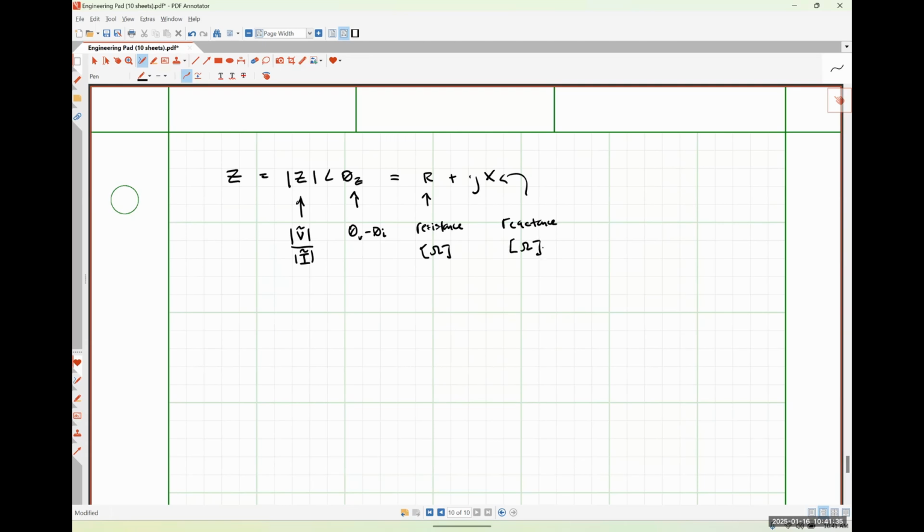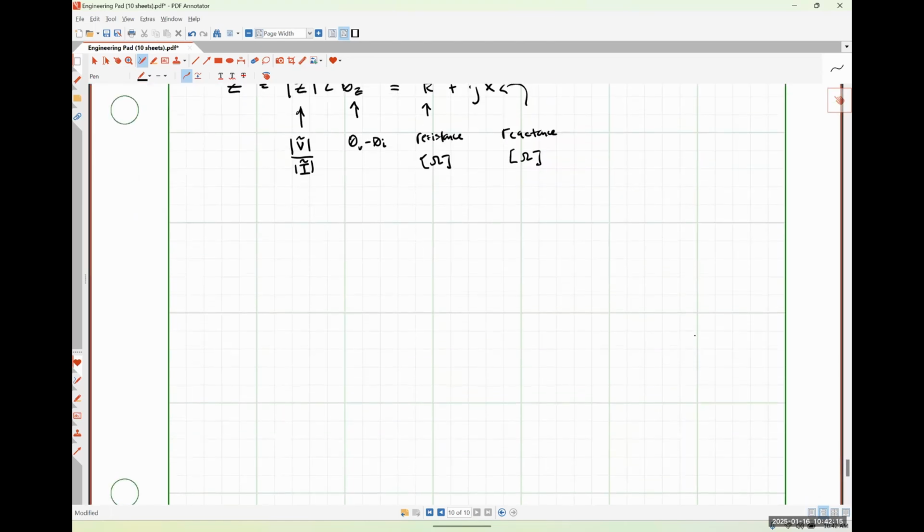measured in ohms. So in this class, we have actually been using X, the reactance, instead of bothering with inductance and things like that. We've been just using the reactance outright, which is why I've been having all of those things where we have resistance and then a JX term, okay? So that's a more common thing to do in power engineering than just bothering with the actual value of inductances and stuff like that. Because when you're working at a fixed frequency, the value of the inductance literally doesn't matter. The reactance is going to be the same, okay? So those are the different parts of impedance, okay?